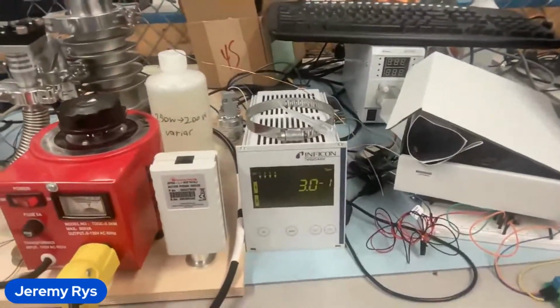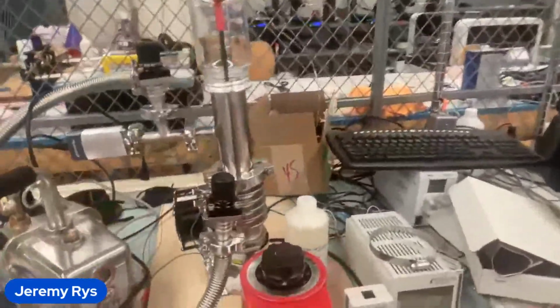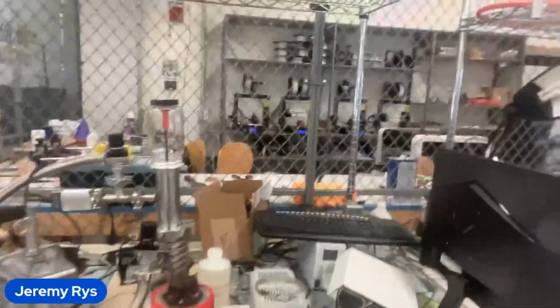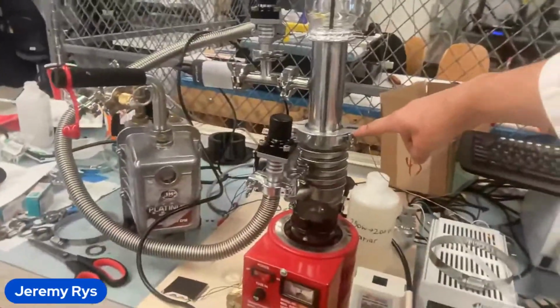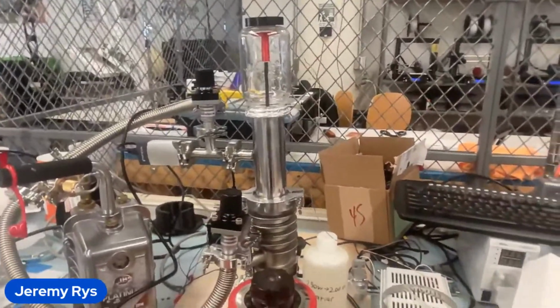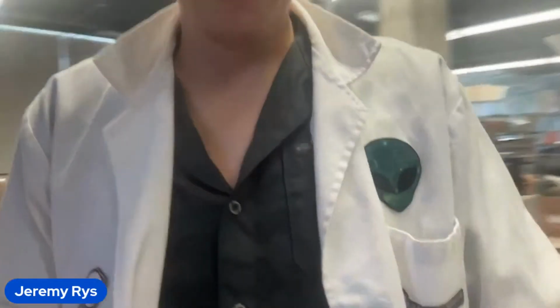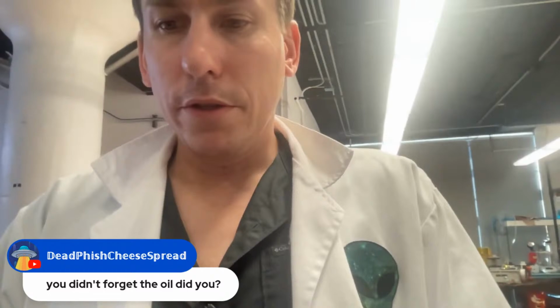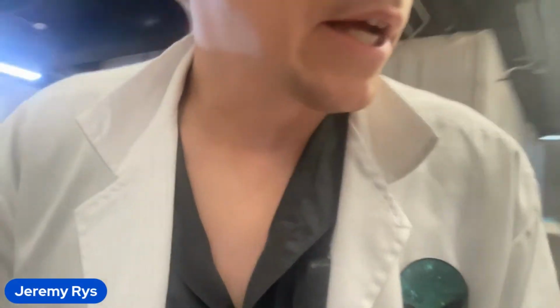So yeah, that will suck it down to closed vacuum, and once we get the vacuum pump up and running, I'm going to let it repressurize again. That way I can open up this flange right here. I'm going to put some gloves on for all that, because even the oils on your skin will contaminate the whole vacuum and screw it up. So you've got to clean everything with isopropyl and then wear gloves. Yeah, we didn't put the oil in yet. I just wanted to demonstrate and show it. So they got that going on.